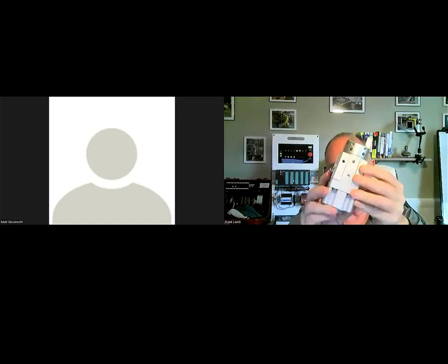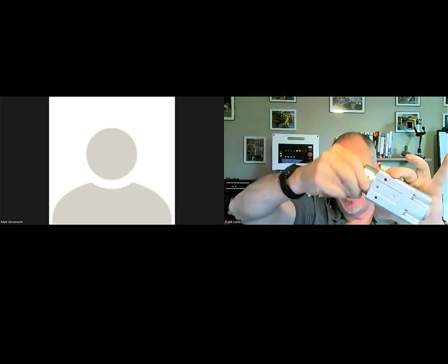This was kind of a cool actuator that I just had sitting around. This is a rotary gripper, right? So you have two ports, one that rotates it one direction, one that rotates it the other. You can mechanically set this and make it stop so that if you don't want to rotate 180 degrees, you can rotate it, say 90 degrees.